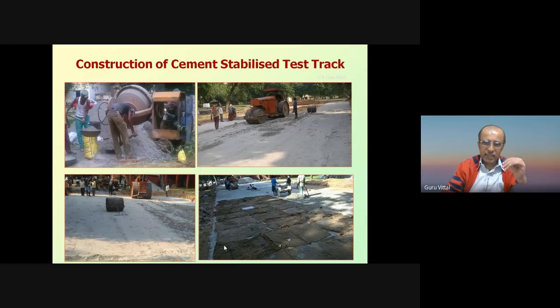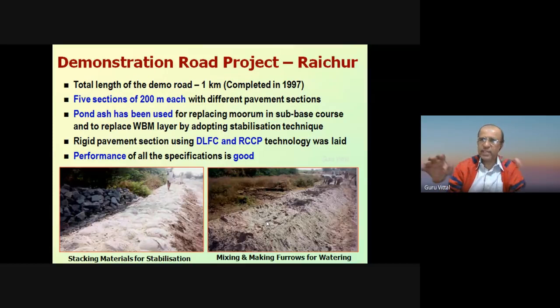Once the stabilized layer has been laid and compacted, it has to be cured. That curing is done by using wet gunny bags, so this is what you are seeing there. The curing process is going on. We don't cure the stabilized layer by water ponding, unlike cement concrete.